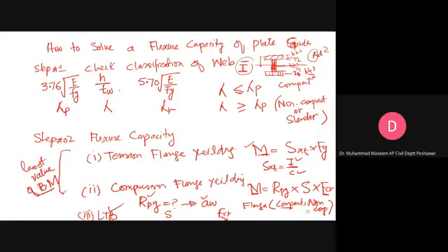Just share that, okay? Otherwise you can go for this: you take this section, you calculate its centroid, you do the math and you calculate the moment of inertia for this section, and you can do it easily, okay? You have a background of engineering mechanics, so it will not be very difficult. You remember in the composite beam we calculate some values, like the moment of inertia of the transformed section. So try to apply that knowledge and let me know whether you are getting the same value or a different one.